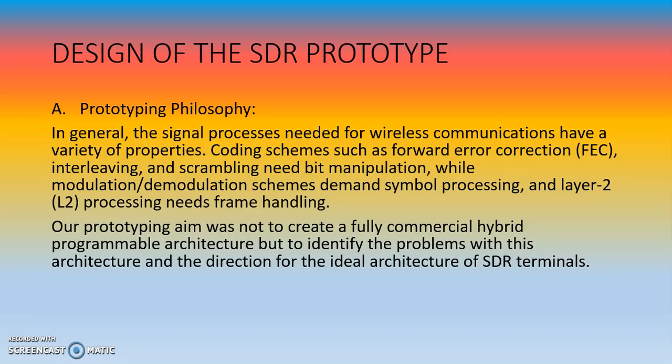First is the design of the SDR prototype, where I want to discuss the prototyping philosophy. The signal processes needed for wireless communication have a variety of properties. For example, coding schemes such as forward error correction (FEC), interleaving, and scrambling need bit manipulation, while modulation and demodulation schemes demand symbol processing and layer 2 (L2) processing needs frame handling.